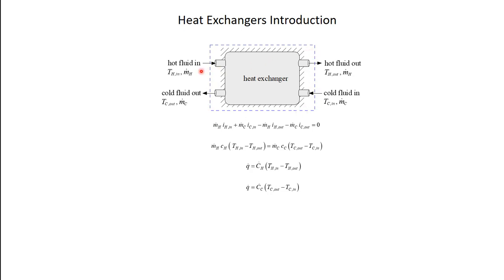And we basically say, we're going to assume the heat exchanger is completely insulated externally. Its jacket is insulated, so that whatever energy is lost by the hot fluid must be gained by the cold fluid, and that's the heat transfer rate, right? So that's this equation here. We're using, again, I for enthalpy because H would just be too confusing. One of the assumptions that we've obviously made right here is that the jacket is insulated, right?